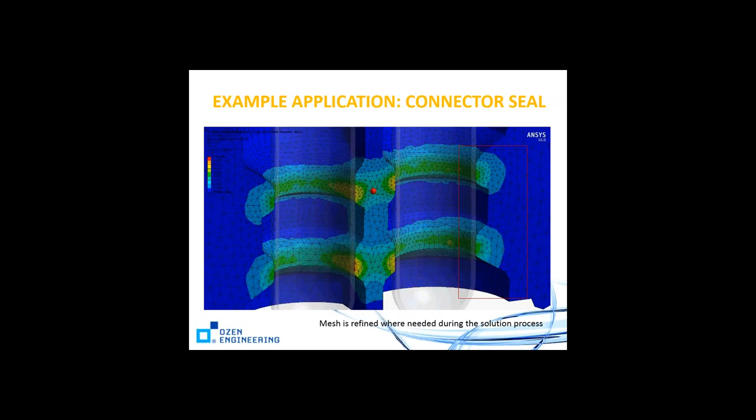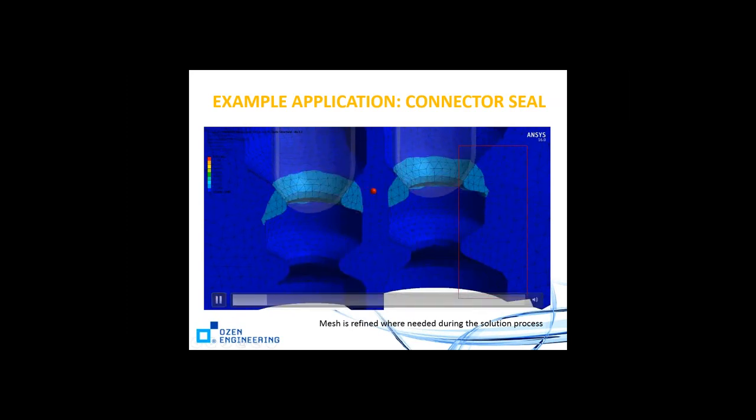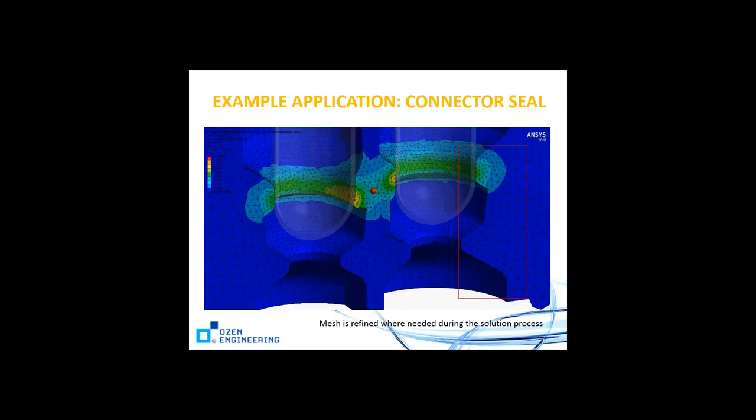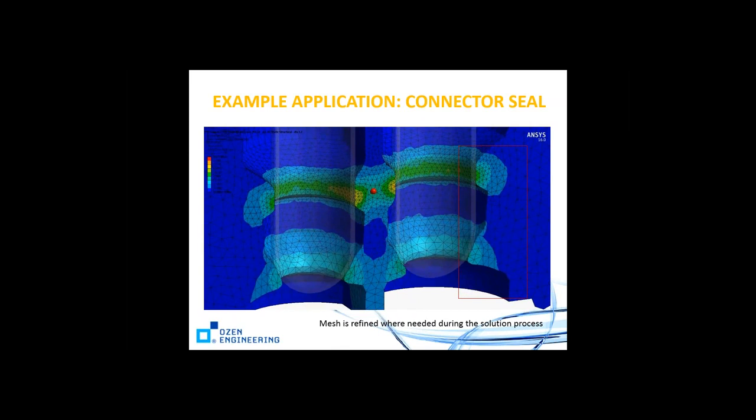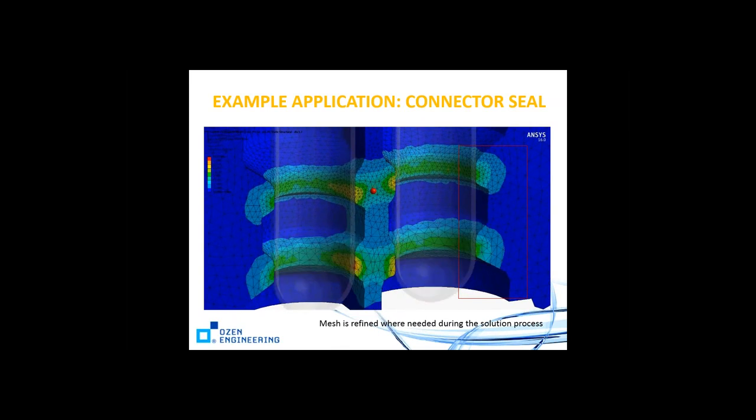As it is solving, it is remeshing the finite element mesh such that it can proceed. Otherwise, with version 15, this problem doesn't run. It stops and says, I can't solve this because there's a lot of distortion of elements. But in version 16, those elements are being remeshed so that you can actually go ahead with the solution. That's an example of remeshing on a transient problem.